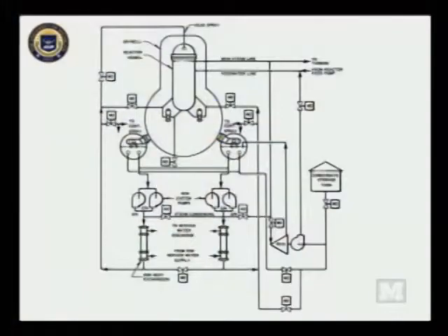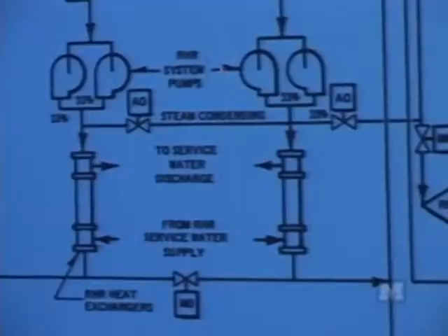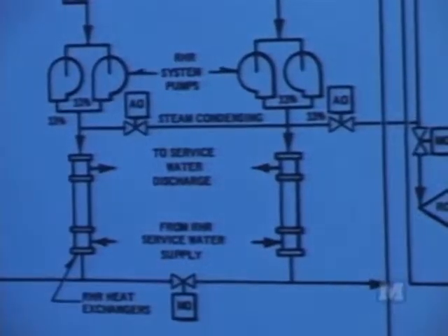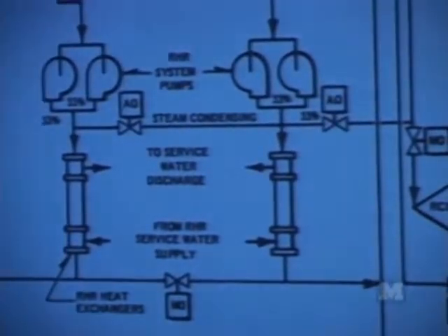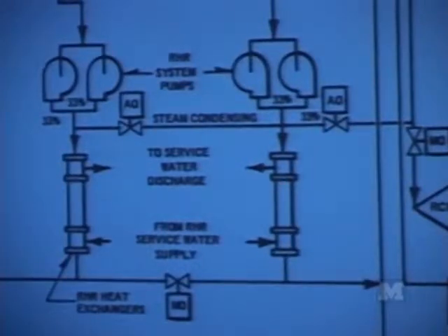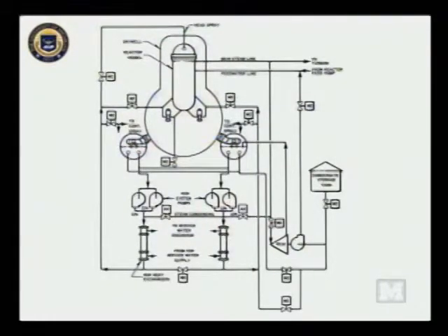And we have here a number of safety systems, but what played a role in the evolution of the station blackout event at Fukushima site is this pump here, which is called the reactor core isolation cooling system pump, which is steam driven and which is part of the residual heat removal system itself. And as many of you know, even after the reactor is shut down and fission reaction is terminated, due to the radioactive decay of many of the fission byproducts, heat is produced, and we need to keep the reactor core covered and cooled. That's where the residual heat removal system comes in.